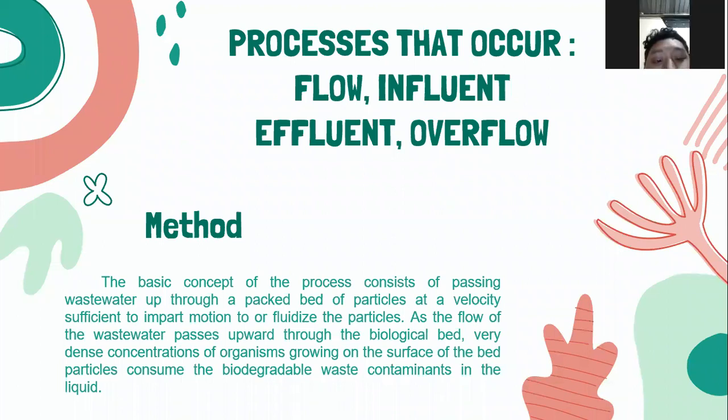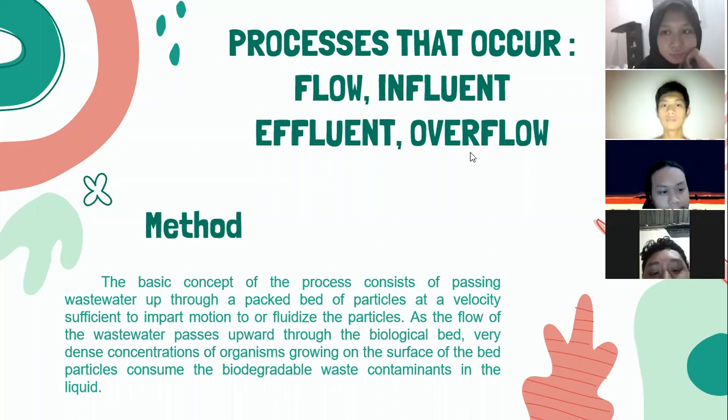The basic concept of the process consists of passing wastewater up through a packed bed of particles at a velocity sufficient to impart motion to, or fluidize, the particles. As the flow of the wastewater passes up through the biological bed, a very dense concentration of organisms growing on the surface of the bed particles consumes the biodegradable waste contaminants in the liquid. Next.